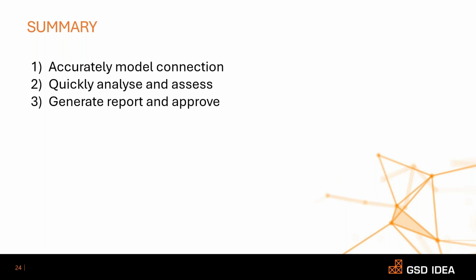So we will be wrapping that up after those 5 examples. What you saw is that with Idea Statica, you can accurately and quickly model a connection, including the components as they were fabricated. In real life, you can include the effects of holes, notches. If you're retrofitting, you can easily iterate to get to the design that you actually need.